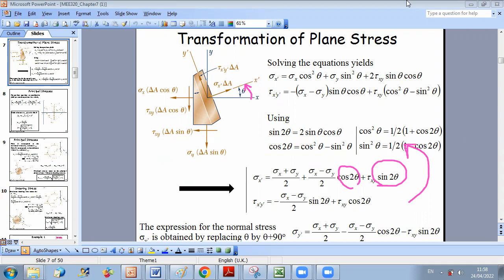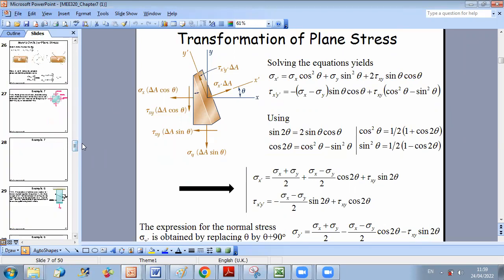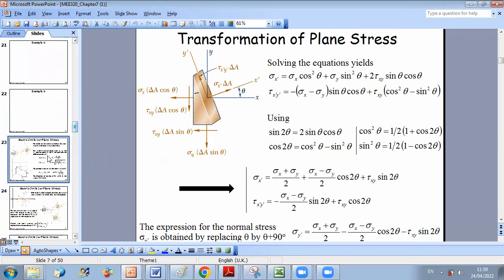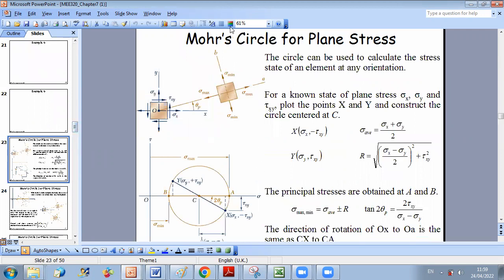Okay, so now going back to your Mohr circle, when I tell you if I rotate relative to x an angle of, let's say, 50 degrees, then you say I should rotate with respect to x here an angle of 100 degrees.